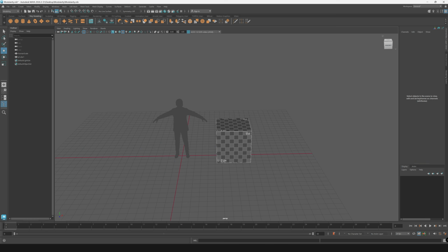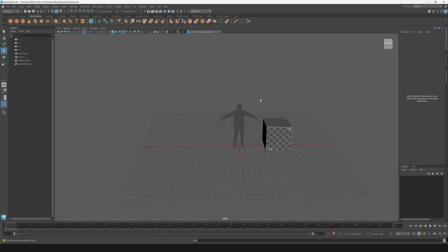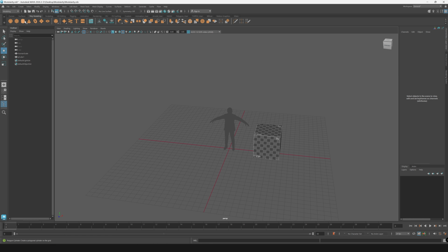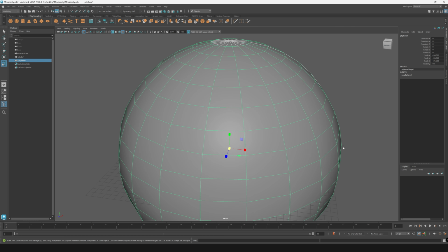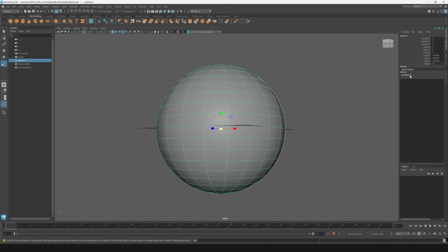So let's hop back into Maya and maybe let's try and do that little rotunda real quickly. The rotunda seemed very large, so we can do a hemisphere like this. Now the hemisphere, we can have however many faces we want here.